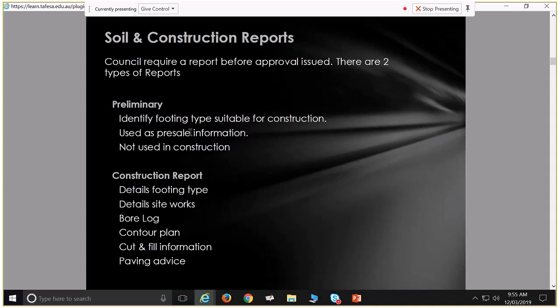Form it up with plastic. So that's your vapourproof membrane that goes underneath your slab. If you form that up as a tube like this that sits inside your piers, you end up having slick sides to your piers, enabling that reactive soil to basically swell up and shrink without actually lifting your piers up, and the base of your piers can lock into that more stable soil at the bottom.